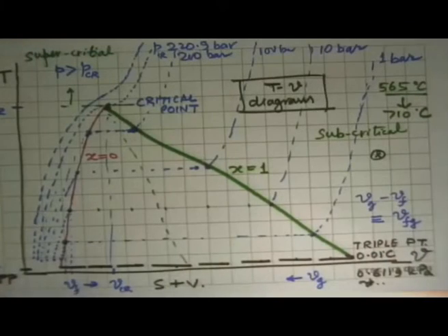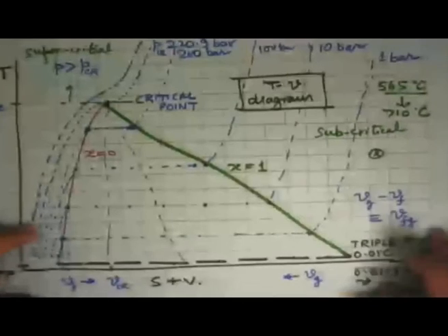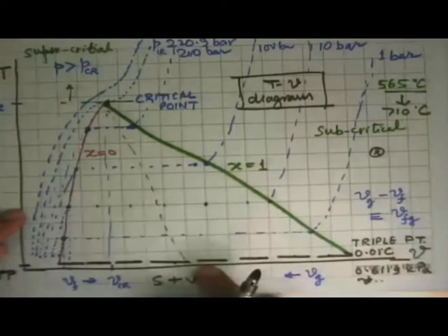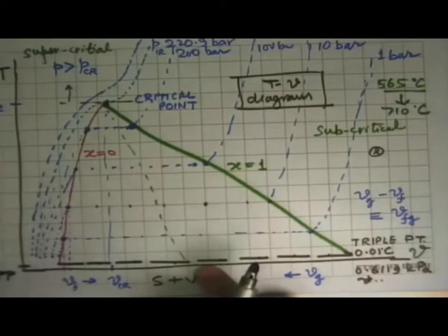And it gives us the ability to tell what will be the state of the substance once two independent properties are known. So if we can locate that the state is, say, here, we know it is a wet saturated state, we can figure out where is the temperature, what is the specific volume, and then calculate all the other properties also.